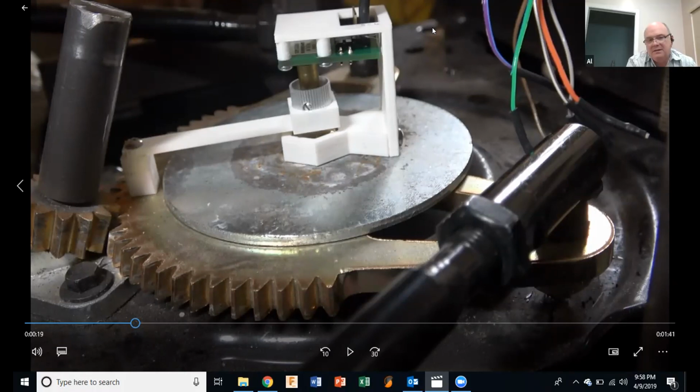Yeah, I think the sensor natively puts out between 0 and 4095, and they just multiply that result by, I think, 0.0876 or something. And if you do that math, you get to 360 degrees. It gives you a float number, which gives you a perceived level of precision. I'm not sure how that would work in practice.